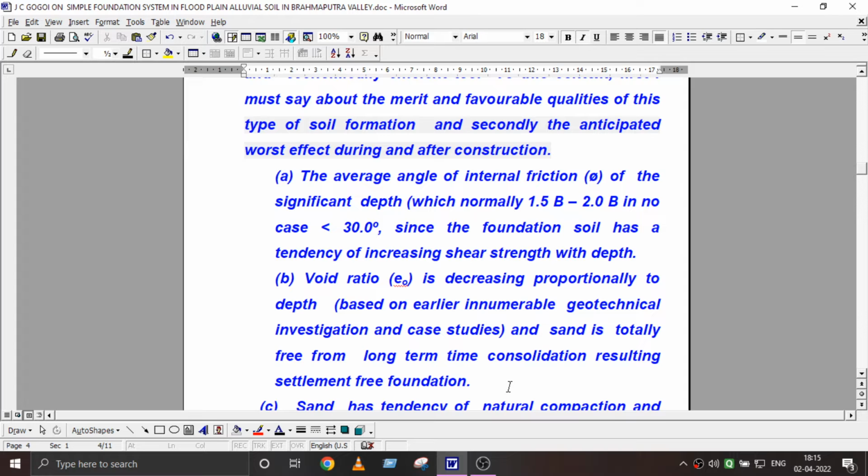When foundation is completed, some amount of settlement is over, and when substructure is completed, then some more amount of settlement will be over. Before 100% load, this settlement shall be completed.